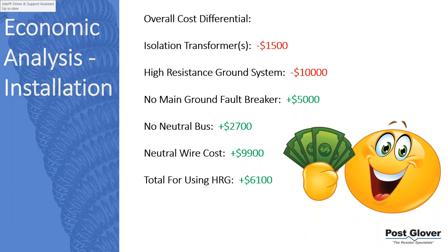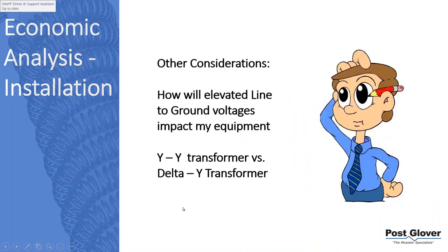Now, that being said, there's always situations where it's very possible that installation on a high resistance ground system is more than a solid ground system. There are a lot of variables, and we'll go through the majority of the ones that we haven't talked about in a second. But the point is that I don't want you to think that HRG is always going to be less expensive on installation. However, I want you to open up yourself to the possibility and also the likelihood that it could be. And so the stuff we haven't really talked about, it is important.